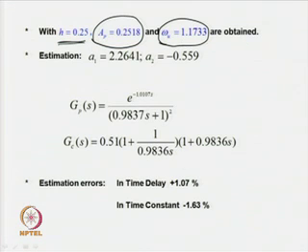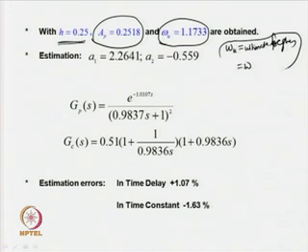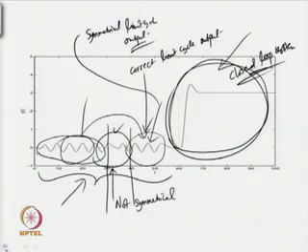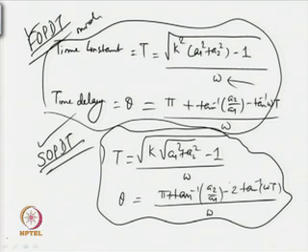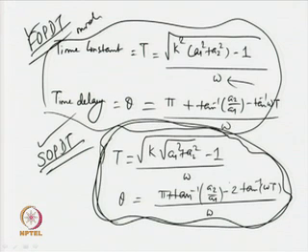Now, for using this value in the formula, I assume that omega u is the ultimate frequency, which is nothing but the frequency omega. So, for all practical purposes, we will use omega equal to omega u. So, when A p, omega u, h are put in the formulae that we have found for the parameters of this second order plus dead time transfer function model, then T and theta are estimated.